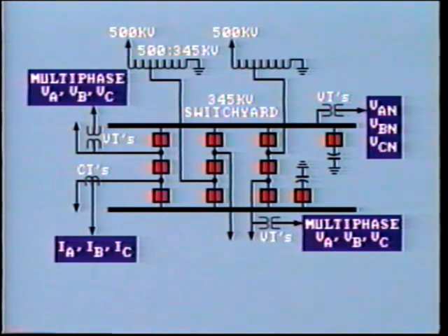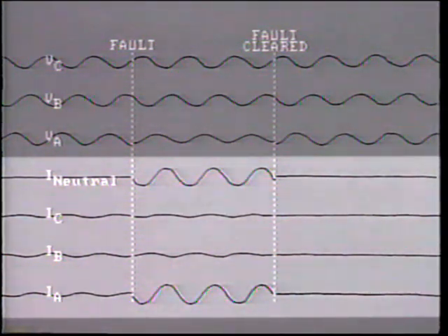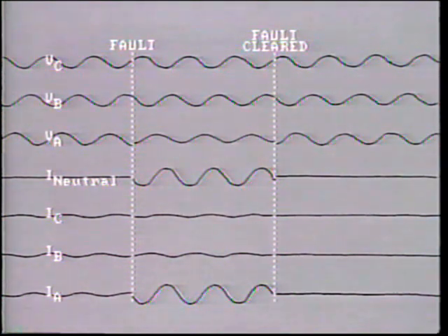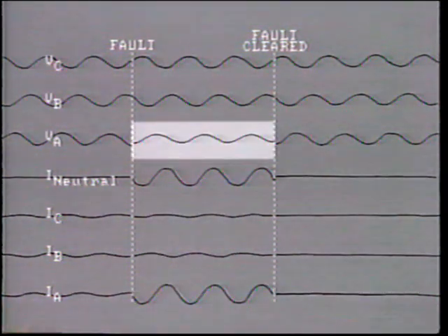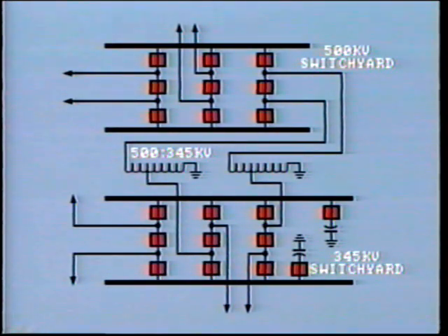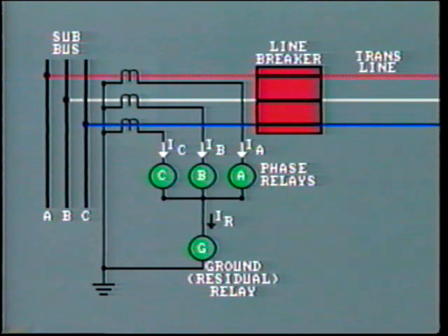It's also important to look at phase current in each transmission line. The current traces can then be compared with voltage traces to confirm which phase or phases were faulted. A sharp rise in current and drop in voltage on A phase, for example, is a pretty sure sign of an A phase fault. Often there are not enough channels to monitor each phase current of every important line. So, quite often, only one phase of each line is monitored, with the phases alternating from one line to another. However, every major transmission line should have its residual current monitored.